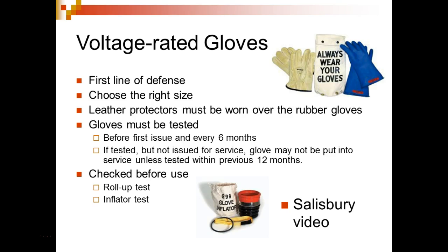Oh yeah, well what happens is you've got magnetic windings, so it's got that really thin insulation on it, that laminated coating, because you've got to get that magnetic coupling, and that stuff will burn off. That insulation is in there to allow the motor to start, and it'll handle a certain amount of overload over a little while, but if you leave it on there, that motor's going to get extremely hot and it's going to burn those windings up.